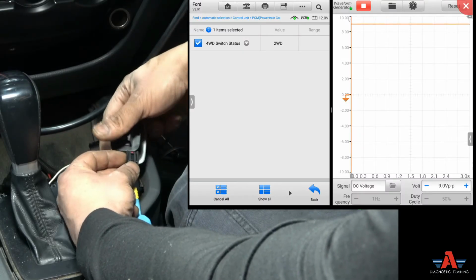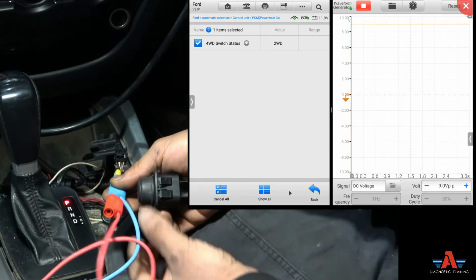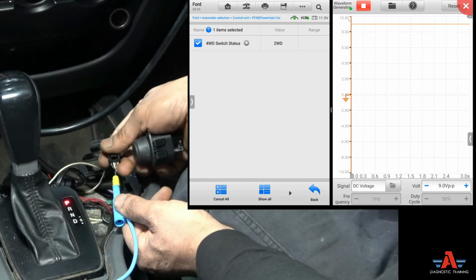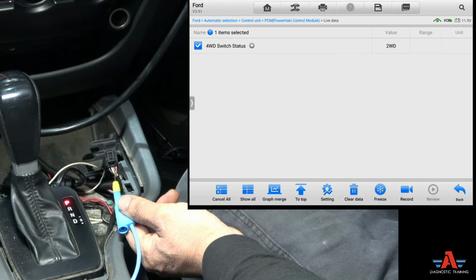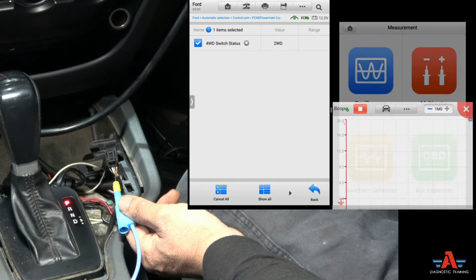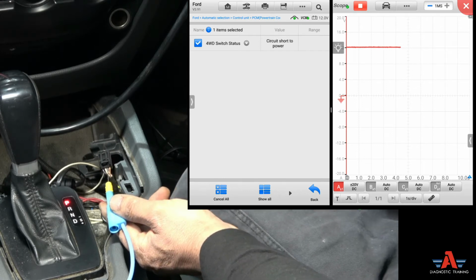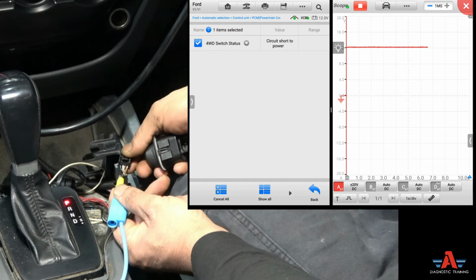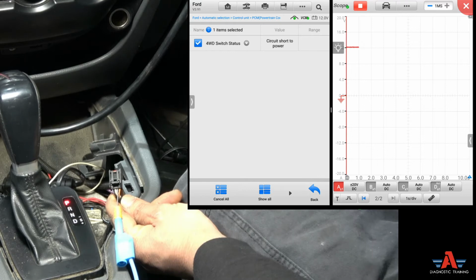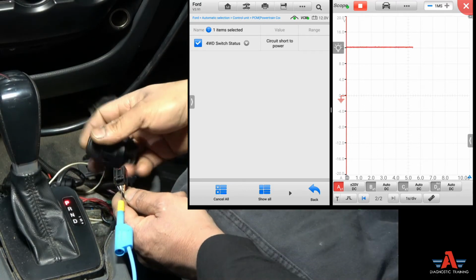Let's put it in and let's see if we can do this. Okay, all right, I'm just gonna take that voltage supply out. We don't need that anymore. I'm still connected to my scope, so let's go back to the scope. Let me grab the oscilloscope here. Let's go plus minus 20, which is good. Right now I'm showing 12 volt on that bias voltage, right? The signal voltage, signal wire. I'm just gonna connect that now to the switch.